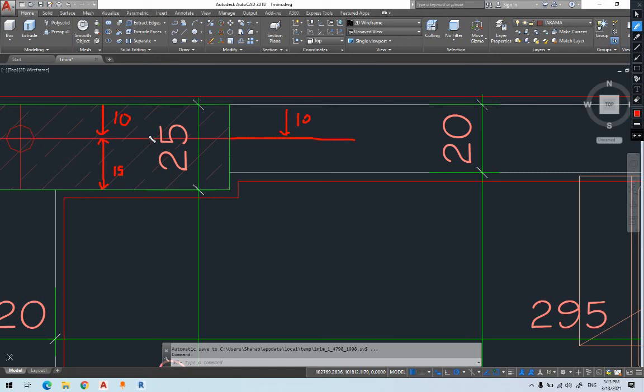So there are two ways. We're not going to move the grid line. Remember, the grid line's locations are specific. We have to move the column. So you have to move the column in order to manage this. You will see how to move them. Don't worry about it. Then, on the other direction, I need to know, yes.